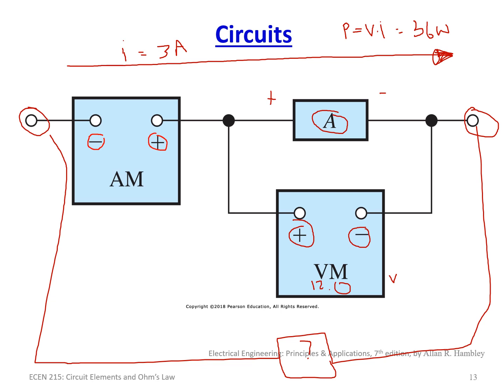amps that is actually flowing through, right? We are going through this direction. We're flowing current through in the direction of the arrow. So the amp meter is going to read, what do you think? It's going to read minus 3 amps because the current is entering the negative terminal and leaving the positive terminal. So the convention on the amp meters is backwards for the way the circuit, the way we've got this example set up.